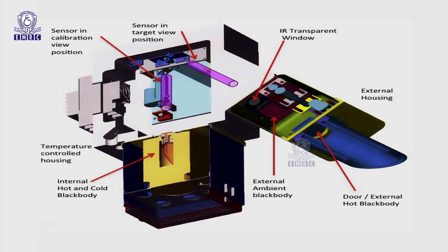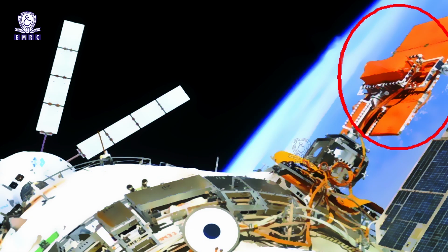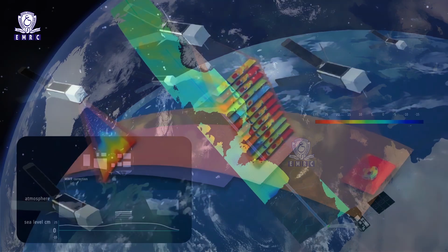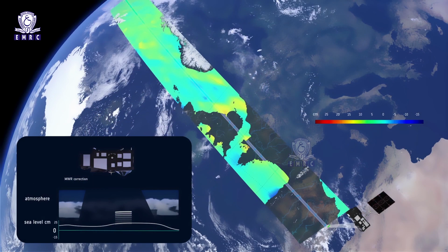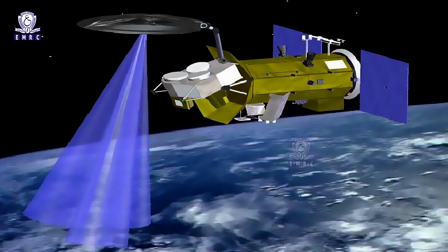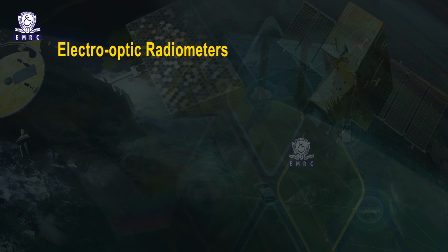A radiometer is an instrument designed to measure the intensity of electromagnetic radiation in a set of wave bands ranging from ultraviolet to microwave wavelengths. The radiometers discussed here are called electro-optic sensors because they measure electromagnetic energy using optical techniques and electronic detectors, though they are only capable of recording a single data value for their view area. If they are mounted in a scanner device, images can be produced.